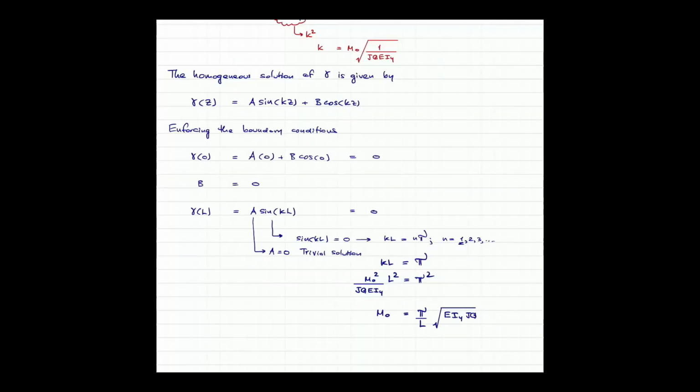So we can find out the magnitude of m naught that is corresponding to the lateral torsional buckling of the steel beam. So we account for the lateral instability that occurs simultaneously at the same time with the torsional buckling. We have some further development for tomorrow, that the cross section will undergo the warping effect.